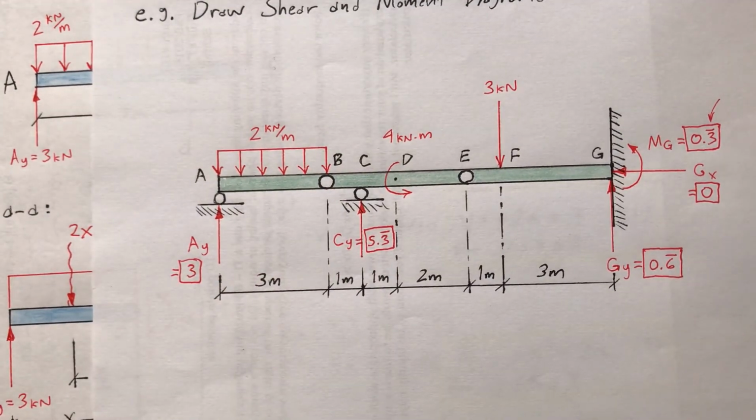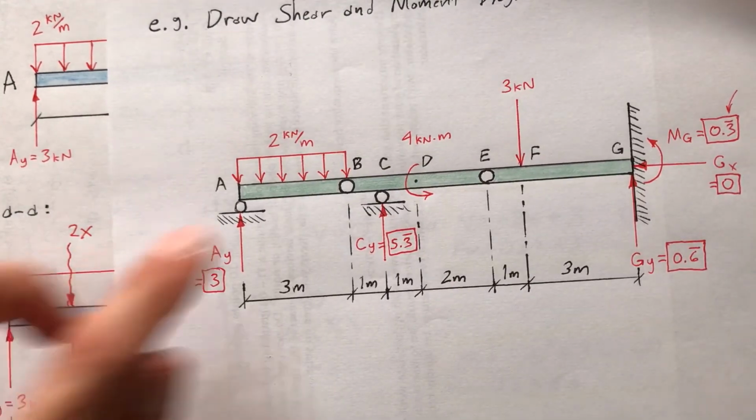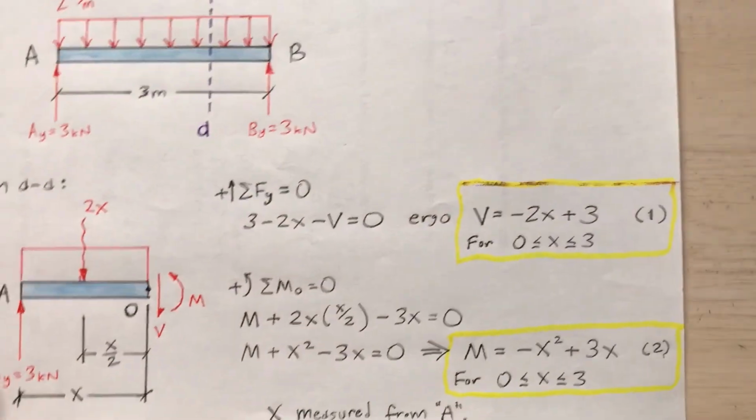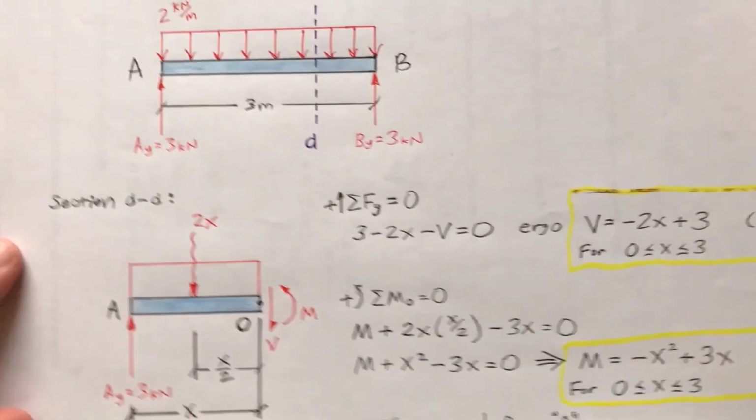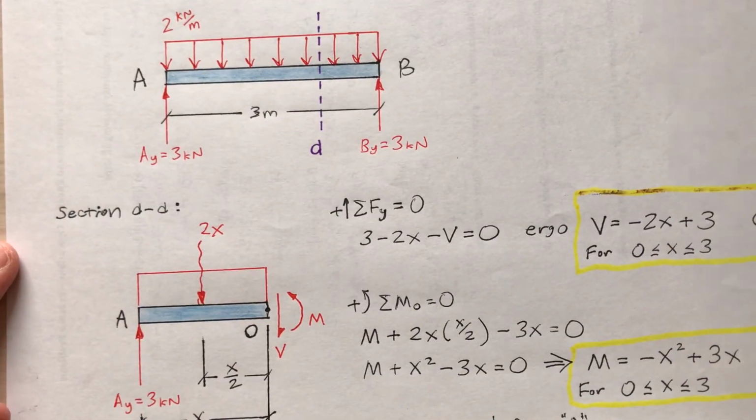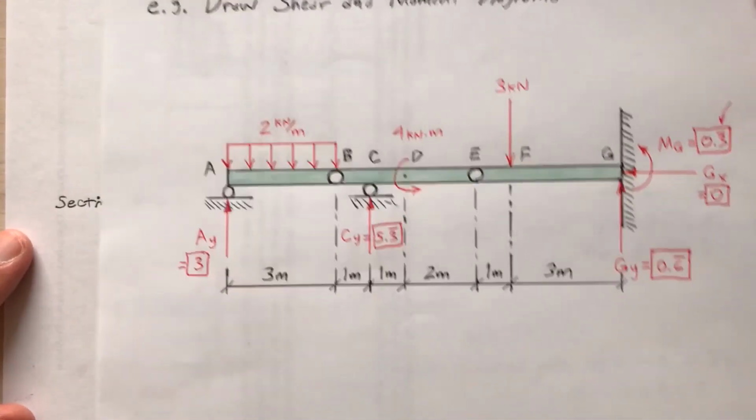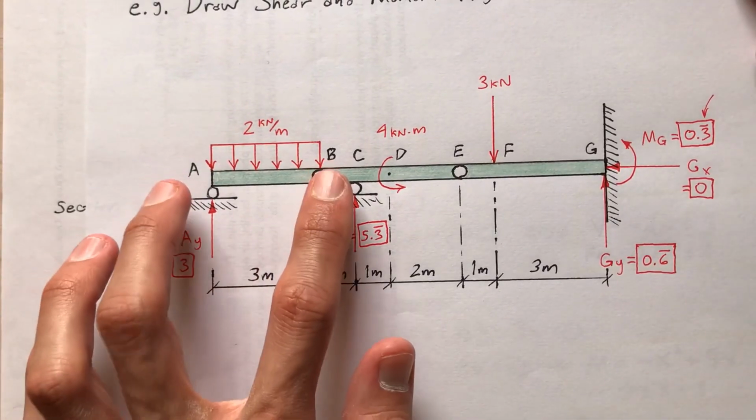So my arithmetic is probably correct. The hinge can't carry any internal moment, and my equation reflects that. So next I'm going to analyze... Okay, so I'm done finding the internal shear and moment for AB.